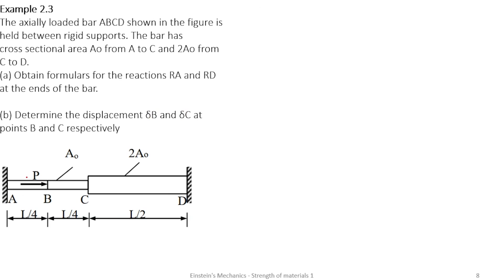So we want what is going to happen in what? AB, because anything that is happening at B is as a result of the force P causing it to happen. And anything happening at C is a result of something happening in what? The entire CD. So I can boldly say that elongation at B is the same as elongation from A to B, which I know the formula as force in AB multiplying the length of AB, over the area of AB and the E.